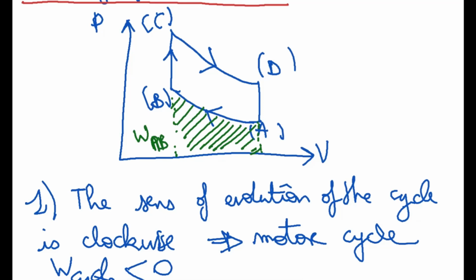And then if you want to know, this process works for every single curve in general. This is a general process. For example, if you want to know what is the work of the specific transformation CB, then you have to take the curve CB and take the area between CB and the abscissa. So if you do that, it will be this area. So the red lines will be the area that represents the work CB, CG.